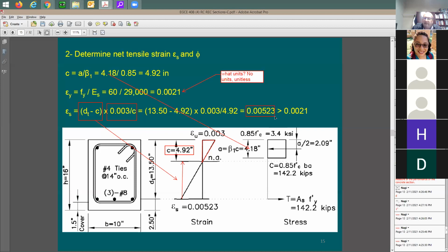This is good. High strain in the steel. This is great because it's going to be more than the yield strain. So my assumption turned to be correct. In some cases, you backcheck the strain and you're going to find it to be lower than this strain. In this case, your assumption that the steel stress is going to be at Fy is wrong, and you need to repeat your work differently. So, okay, now I was able to prove here that the strain in the steel is higher than the yield strain. Now I need to take this value back and also check the phi factor.